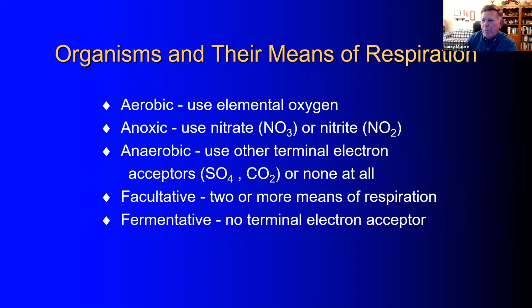If you operate at about a 3 or 4 day sludge age, most of that BOD is going into the growth reaction. You're going to produce a lot of waste biomass, but your oxygen demand will be lower. If you're an oxidation ditch operating at a 30-day sludge age, you're not going to generate a lot of waste biomass, and most of the BOD load is going to be channeled into the energy reaction. You're going to need more oxygen.